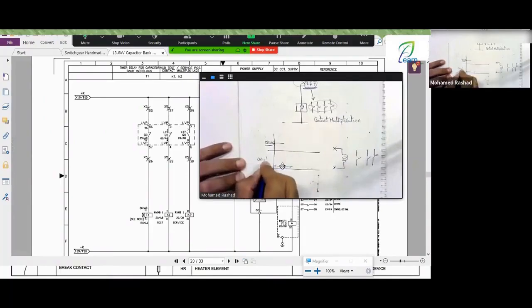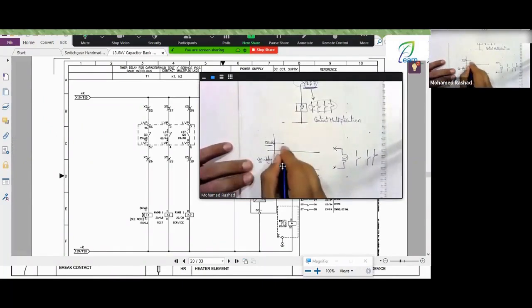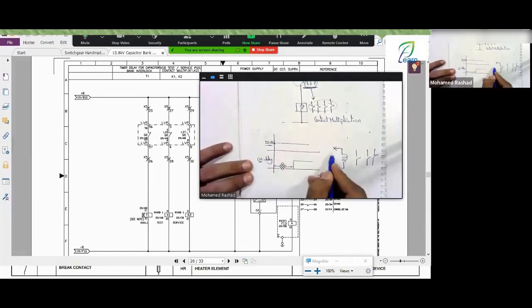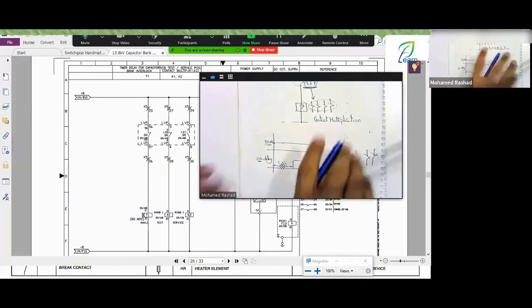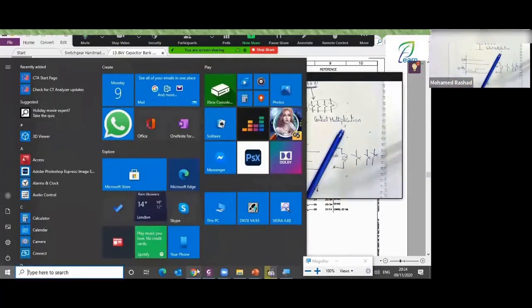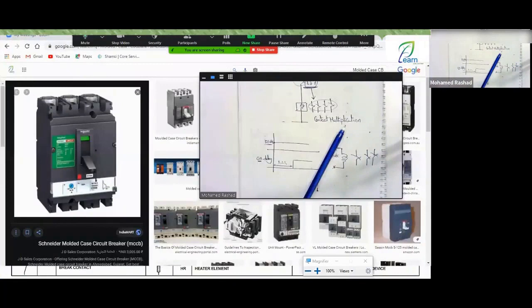This is an on delay, meaning it is on, but after a delay time. Meaning a delay period. It stays without engaging, it waits for a period, and then it changes its contact positions and starts working. So as soon as you apply 125 volts DC, it first counts the time. 1 second, 2 seconds, 3 seconds, depending on the setting you have configured. Then what does it do? It changes its contact positions, turning the normally open to closed and the normally closed to open.